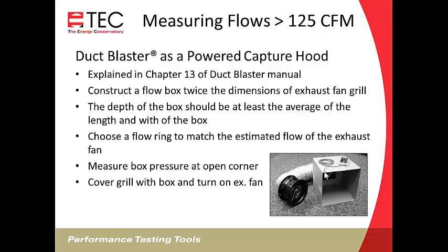So you'll cover the grill with the box and turn on the exhaust fan. And again, you need to have a pretty tight seal in order to get an accurate measurement. Although it's not as critical, because you're going to have zero pressure at this location, and if you have zero pressure, you're going to have zero flow. So a really tight seal isn't as important with this method. And then you'll turn up the Duct Blaster fan to zero out the pressure.